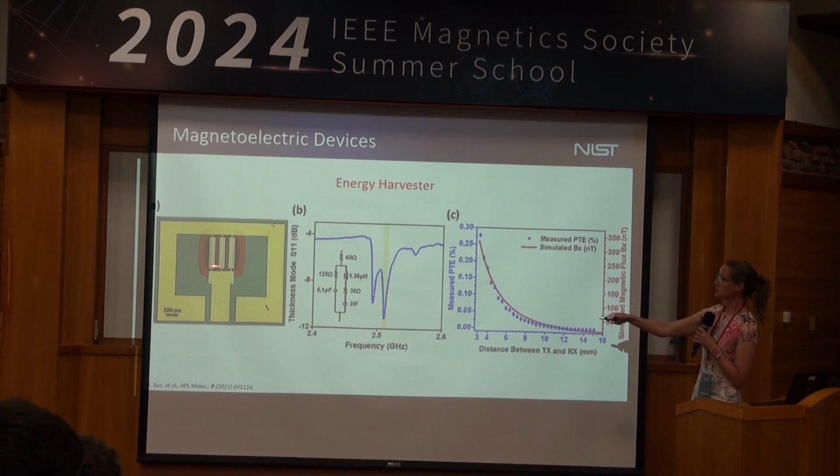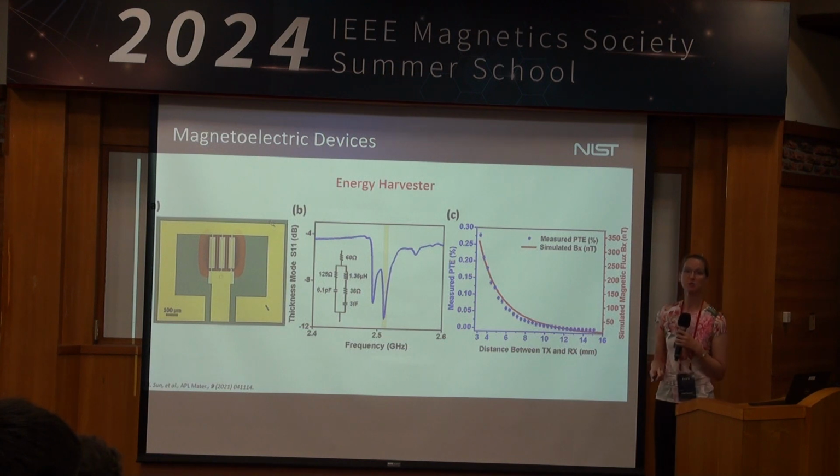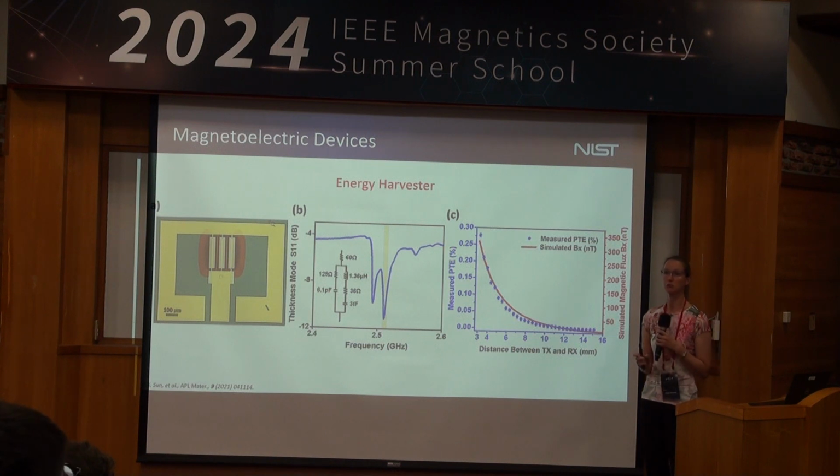And this is what's called a dual band, because one of the limitations of these is they're tuned to work for a specific frequency range. So you can see one band is operating in this frequency range, another band is operating here. By combining them, you're able to enhance the absorption over a much broader range. And then one of the nice things with these is that they have a much better power transmission efficiency than any coils that you can make. And they're pretty insensitive to offsets and angle variations in them. And the improvement is 1 to 2 orders of magnitude currently. So it's not a small variation.